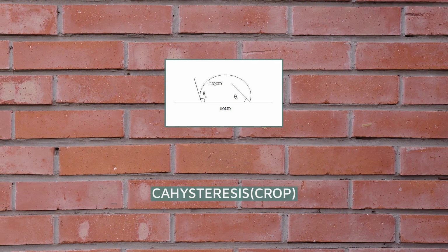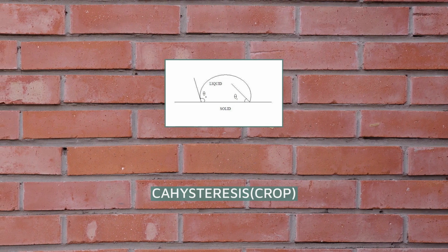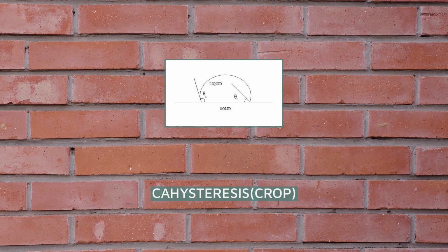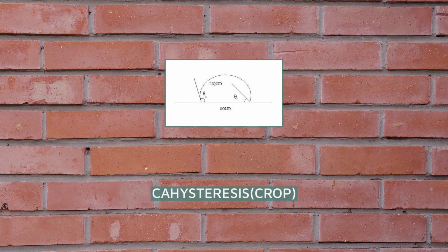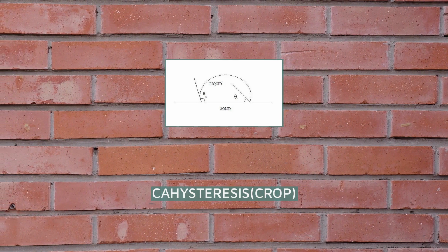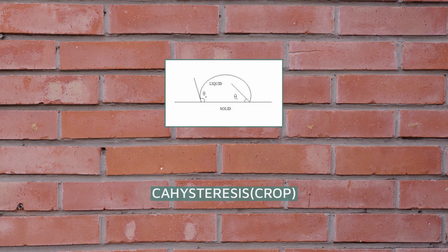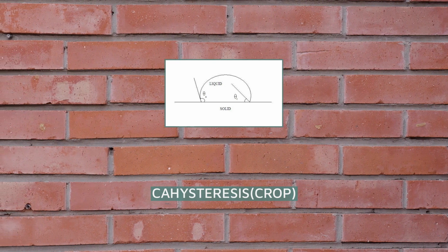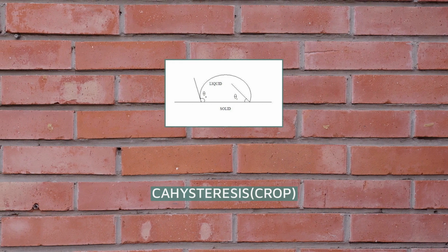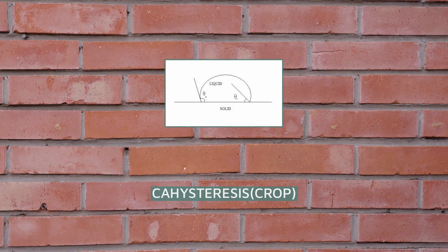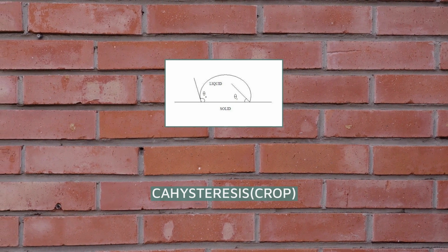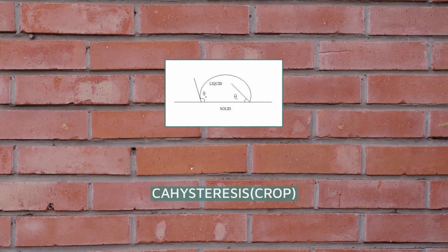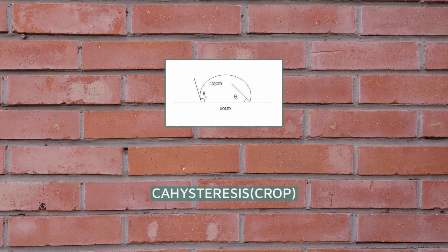A well-known departure from ideal conditions is when the surface of interest has a rough texture. The rough texture of a surface can fall into one of two categories, homogeneous or heterogeneous. A homogeneous wetting regime is where the liquid fills in the grooves of a rough surface. A heterogeneous wetting regime is where the surface is a composite of two types of patches. An important example of such a composite surface is one composed of patches of both air and solid.